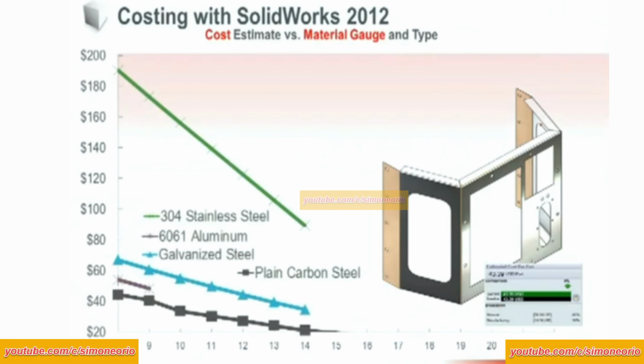So let's take that same kind of information and apply it to my graph. So as we'd expect, as the thickness goes up, my costs increase. So where we want to be is right here at my minimum requirements. But I get a lot of feedback here, right? And whether I'm evaluating different materials or different geometry options, I can see that what I select either has a big impact or a smaller impact. So I could easily use galvanized steel or plain carbon steel. Yeah, it's pretty much the same. Then I get up to stainless steel and I see that that's really where I get the cost that's going to be about 3 times higher, running all the way up to about 10 times higher depending on the thickness that I use. So I'm starting to put these pieces together and connect these dots.